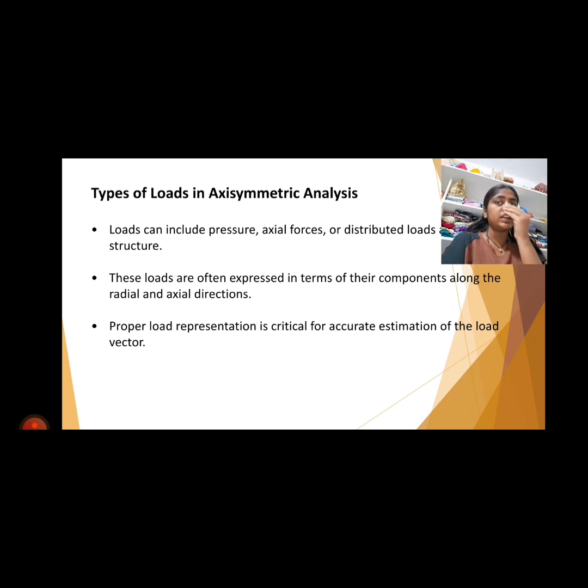The governing equation is the finite element equilibrium equation, Ku equals F, where K is the global stiffness matrix, U is the nodal displacement vector, and F is the global load vector. Accurate estimation of the load vector and stress components is essential to solve this system reliably.